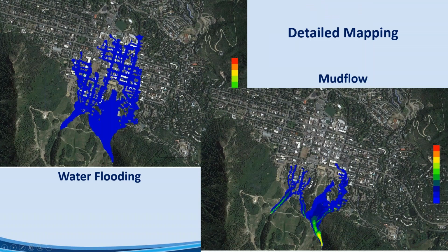So if you show them the inundation mapping, you can see this is all mostly shallow flooding in here, whereas the mud flow comes in and deposits deeper depths coming out of the alluvial fan, some deeper depths in here, and the flow's not going very far because the flow ceases as a mud flow event. But here the water continues on down through the urban area.